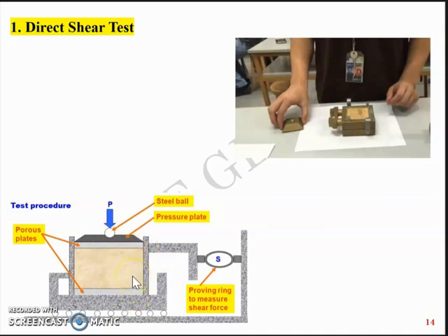So it's called a direct shear test because you are applying shear stress directly into the soil mass. In the earlier videos we said that rarely soil is applied directly by the shear stress, and usually what happens is the compressive load, when acted upon an inclined plane, is transferred as a shear stress. But in this particular test, we are directly applying a shear stress onto the soil.